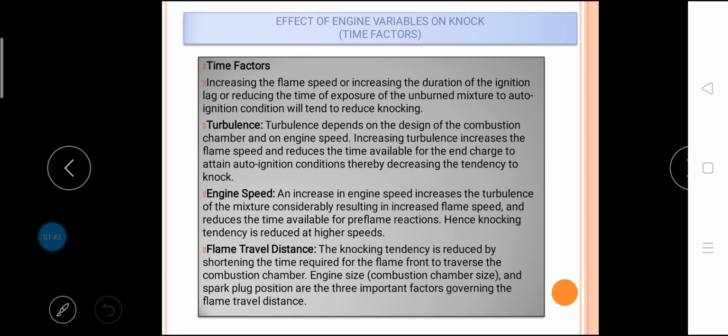Octane value of the fuel. A higher self-ignition temperature of the fuel and a low pre-flame reactivity would reduce the tendency of knocking. In general, paraffin series of hydrocarbon have the maximum and aromatic series the minimum tendency to knock. The naphthalene series comes in between the two. Usually, compounds with more compact molecular structure are less prone to knock. In aliphatic hydrocarbons, unsaturated compounds show lesser knocking tendency than saturated hydrocarbons, the exception being ethylene, acetylene and propylene.